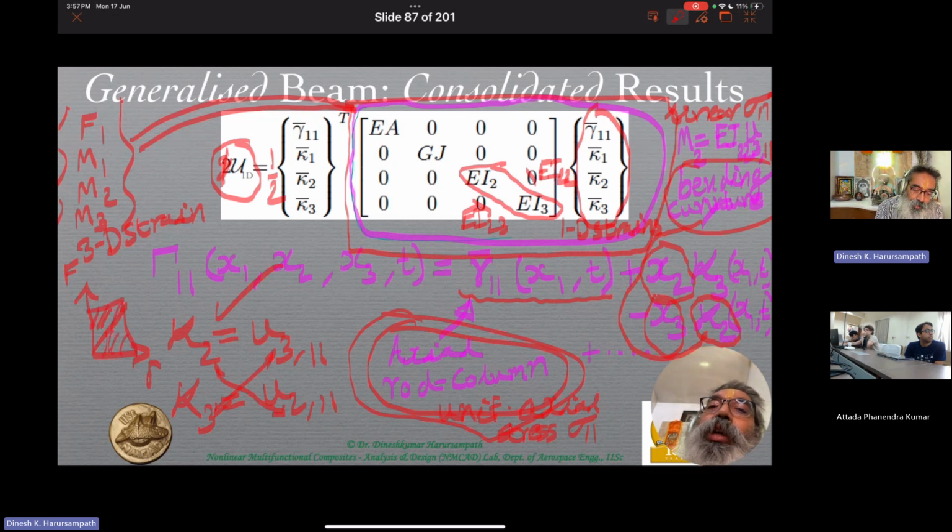The other half is going to give you the complementary strain energy density. In a linear spring, both are equal in magnitude to each other. On the other hand, here we are talking of an actual strain energy which is building up within the beam or the shaft or column or whatever you want to call it, the axial rod, etc. So in any case, this is essentially what is happening.